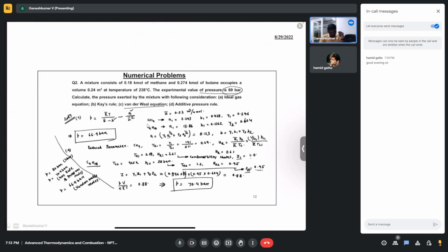They wrote 8.113 and I'm getting 2.848. Yes, sir, exactly. I got the same. I calculated it further, and because it was a simple calculation, I received pressure as 95.18 bar. It's a little bit higher, and earlier it was told that normally the ideal gas relation gives the maximum pressure. But I think the problem here is what you calculate is A power 1 by 2.